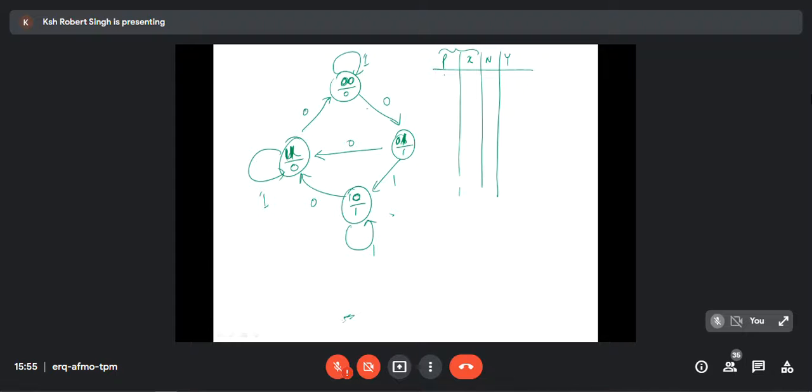Shall we do it using JK flip-flop? Okay, now let us do it using JK flip-flop. Let us design a circuit using JK flip-flop. So 2 bits, so 2 flip-flops: JA, KA, and another flip-flop, JB, KB, because I'm going to design using JK flip-flop. So JK should come here, Y should come at the last, doesn't matter. Okay, this is my next step.